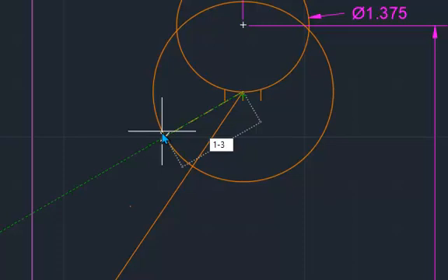1-3/16. And if you're not sure how to put in fractions, which you can do, you can't hit the space bar because that's going to be enter. So what you have to do is put the inches, in this case 1, and then a dash, and then you put your fraction. It works every time. Sometimes I have to remember it because I don't use fractions very often.